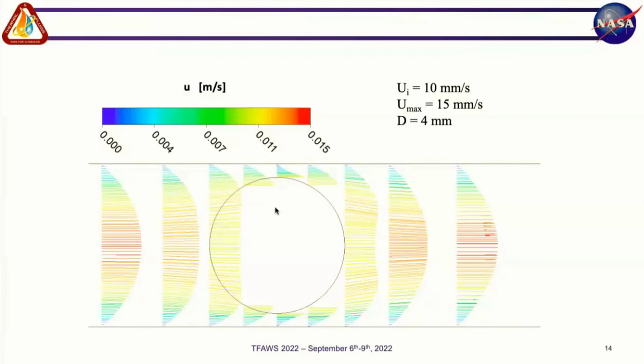What we see is right here at the small gap between the particle and the wall of the channel, the velocity distribution shows a much higher velocity than the distribution that we had if you didn't have the particle in there. So the particle accelerates the flow at the gap between the particle and the wall. And of course, this flow acceleration will enhance your heat transfer process right there. So now we have this heat transfer process that's enhanced around the particle location. And now we know, at least from a qualitative description, what is happening.